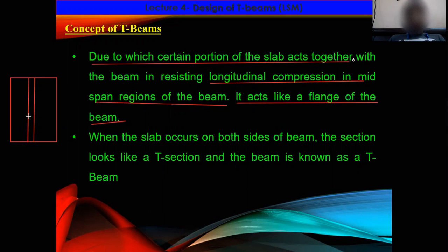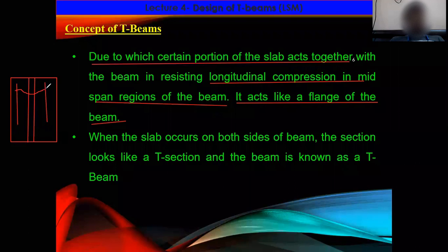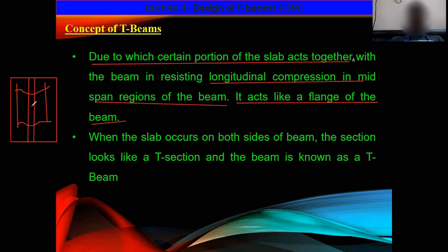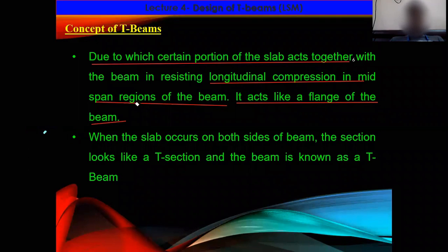This will be considered the span region of the beam. It acts like a flange of the beam. So for this beam, this portion and this portion, some portion of the load will transfer to this beam, right? If I cut this, this will act as a T-beam. I will show this diagram for your understanding.